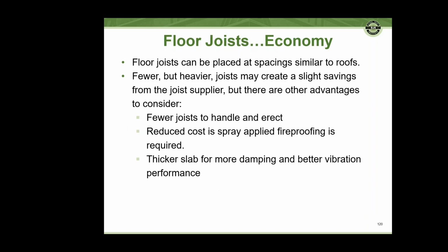Some notes about floor joists. In general, floor joists can and should be placed at spacing similar to roofs. There are a number of advantages to fewer but heavier joists. There could be some savings to the joist manufacturer and in the joist price from supplying a few less joists, but also there are other benefits in terms of fewer joists to handle and erect.